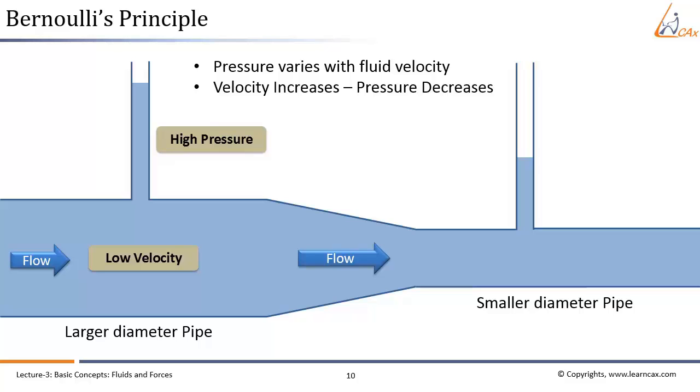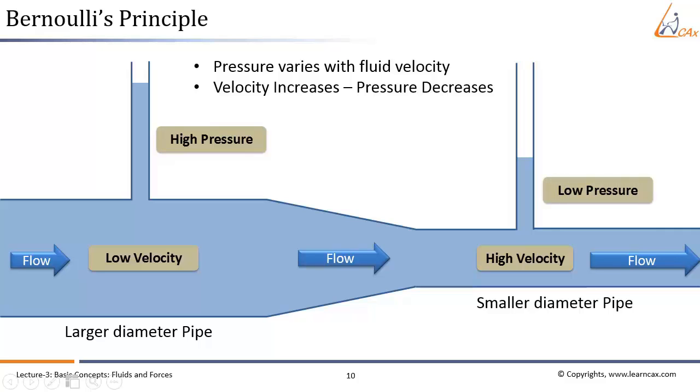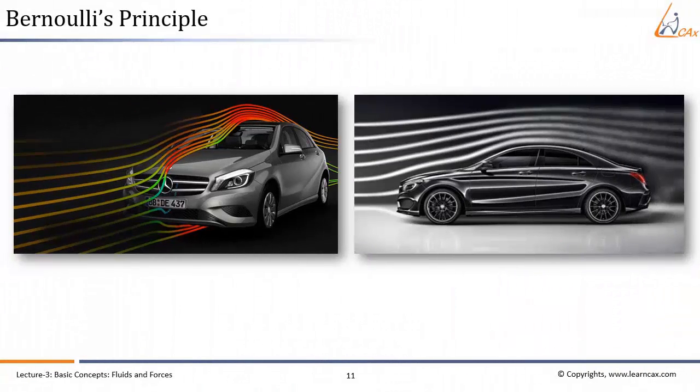Because the water doesn't compress, fewer water molecules pass through the gap at a single time. This means that the rate at which the water flows through must increase. That is, the velocity of the water must increase, accompanied by a pressure reduction. The situation is the same for an external flow also.